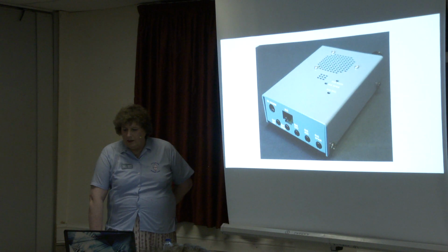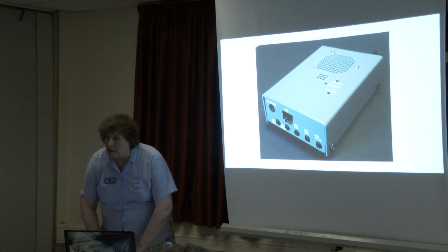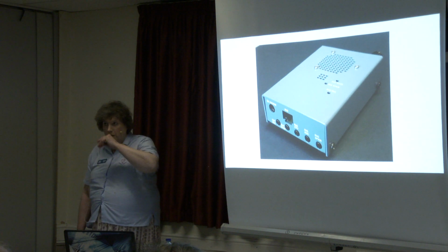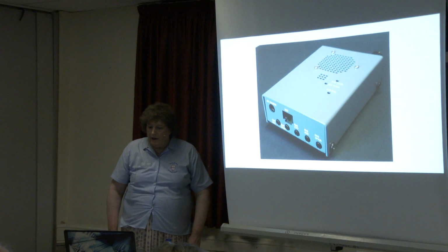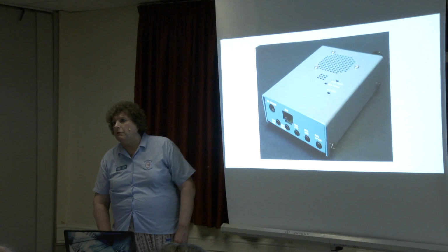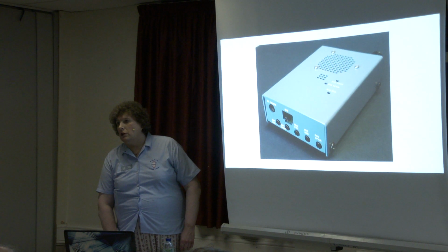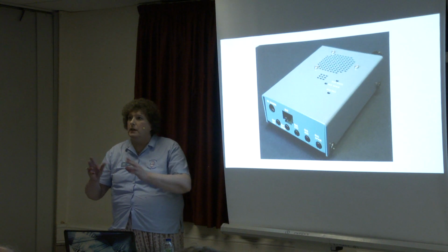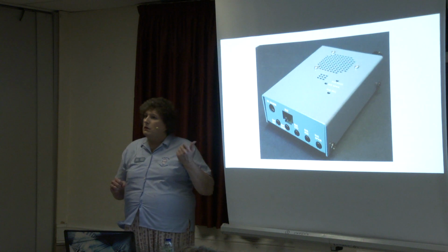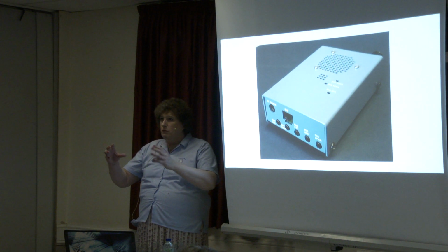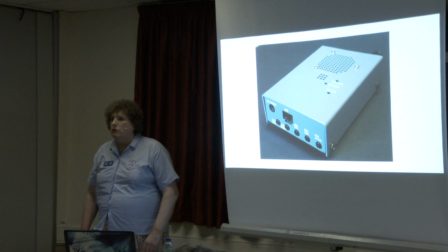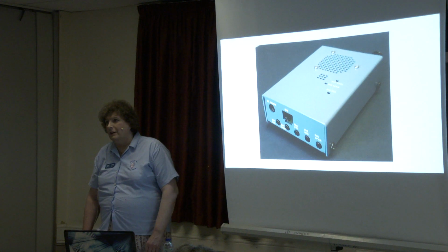That's true. The difference with the broadcast stuff is the bit rates are different, and the bandwidth is considerably different. The higher your bit rate, the more errors you have over a long path, and the more prone it is to phasing and multipath distortions and things like that. But because we've got this down to about an average of 700 bits per second, it is generally stable as a rock.